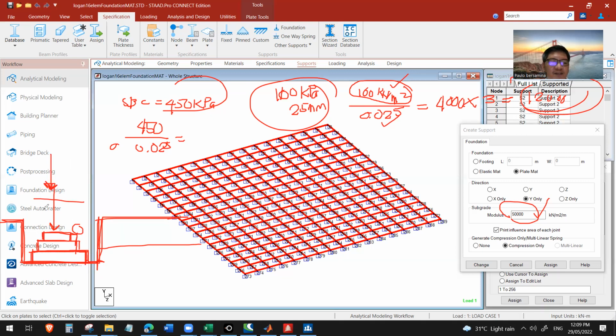Actually, what we used was a truck. We had an ELF truck on top, and its wheel is here. So the load of the ELF truck itself is our load. Then incrementally, using a hydraulic jack that exerts force on the ELF and then on the plate, we measure the displacement, so you come up with a load versus settlement, a load deflection curve.